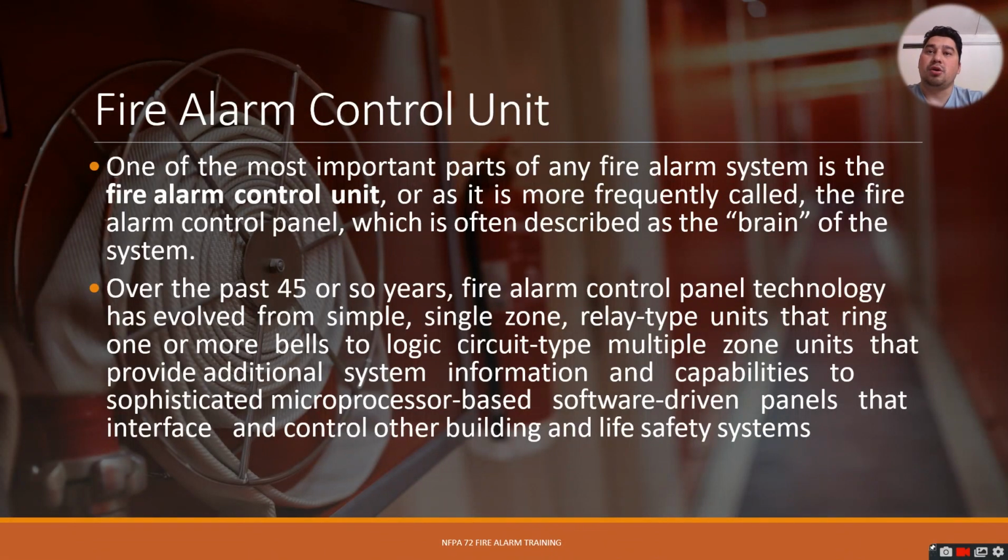Over the past 40 or so years, fire alarm control panel technology has evolved from simple single zone relay type units that ring one or more bells to logic circuit type multiple zone units that provide additional system information and capabilities, to sophisticated microprocessor based software driven panels that interface with and control other building and fire safety systems.